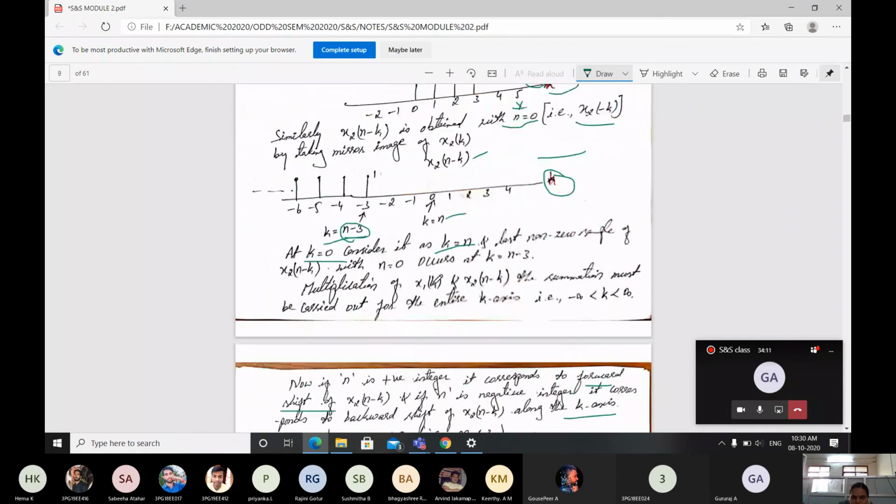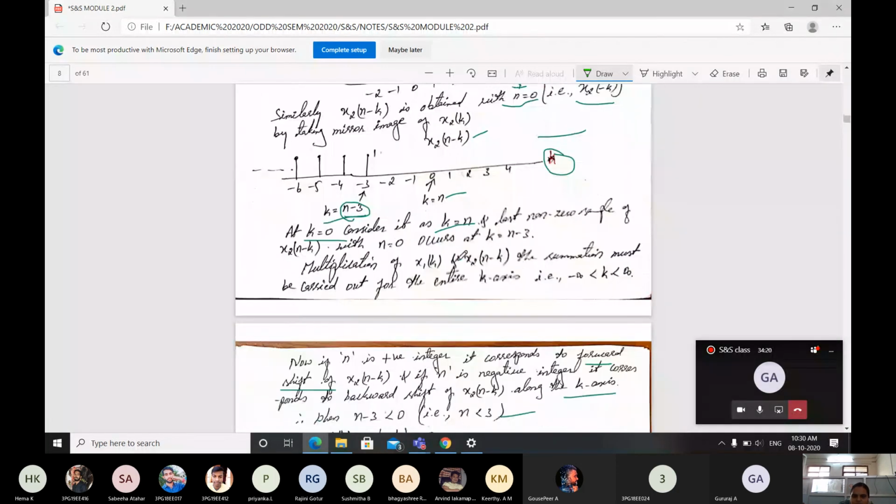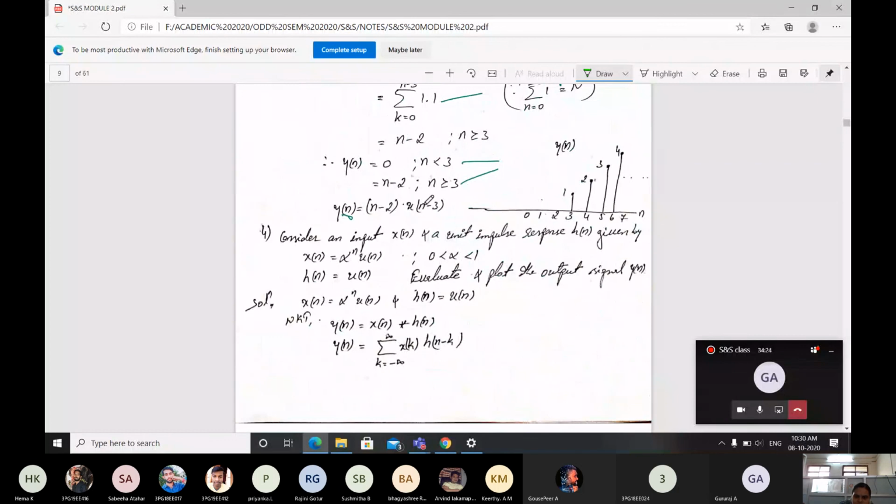So we will be at the u of n minus 3 signal. Then substitute for greater values. Then 1, again minus 2, again. If I substitute n as 3, then 3 minus 2, 1 you will get. From the third position we will be getting the sample. For that reason, start substituting for n starting from 3 only. You don't need to substitute 0, 1, because our u of n minus 3 will start from the third position.